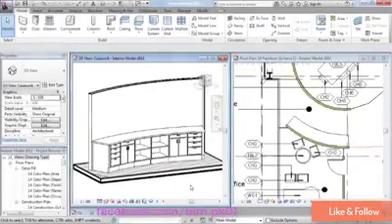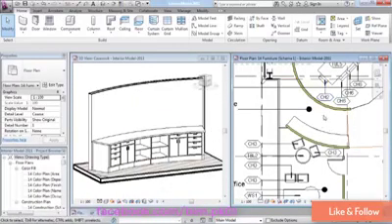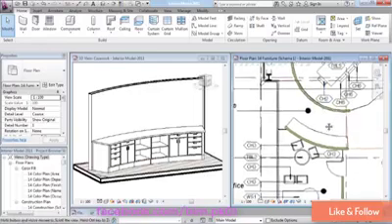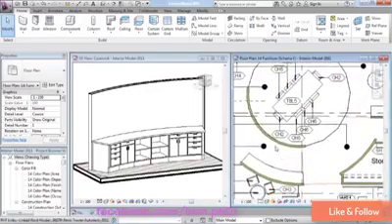What I want to do is go into Revit here, and I want to show you an example of each of the three kinds and talk about these just a little bit more carefully. Over here on the right-hand side of the screen, I have a floor plan. It's a pretty typical floor plan. And you see some examples of walls that are on screen. And walls is a great example of a system family. Walls are built into the software. What it means to be a wall in Revit is predefined by Revit. You and I can't customize what it means to be a wall.